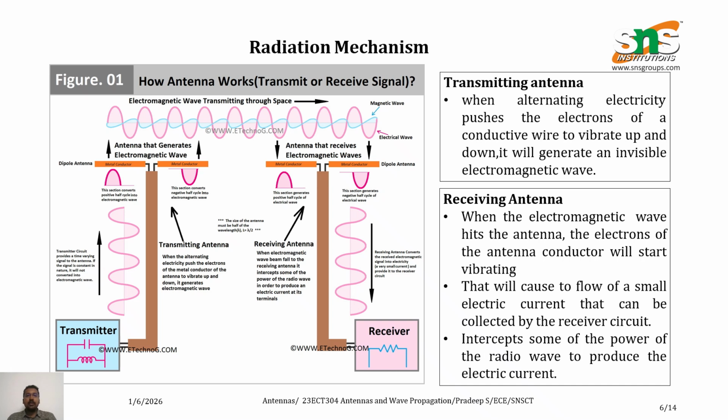Applying voltage across a two-conductor line creates an electric field between the conductors. Electric lines of force act on free electrons, forcing them to displace and create a current. This movement of charges generates a magnetic field. The creation of time-varying electric and magnetic fields forms electromagnetic waves that travel along the line.